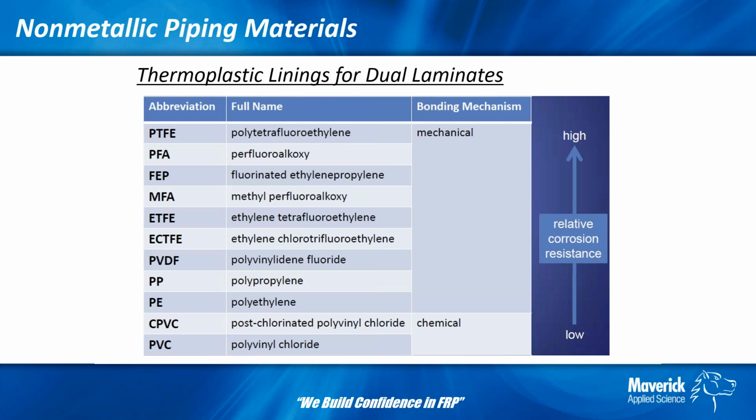That's best practice. The reality is everybody's trying to squeeze every extra day, every extra year they can out of the pipe. You have a pipe that has a design factor for pressure of 10. Generally, from a design standpoint, looking at all influences, it's more like a 6. So once you go through that lining, you're into the structure and compromising the design of the pipe. You can buy a little bit of that. If it goes from a 6 to a 4, that's not a big deal.